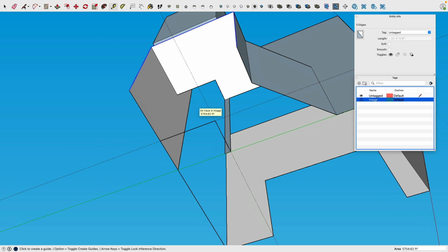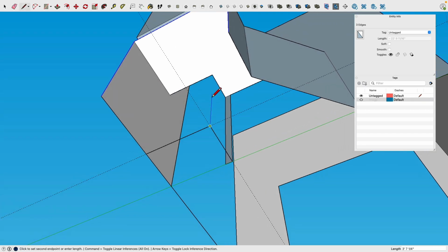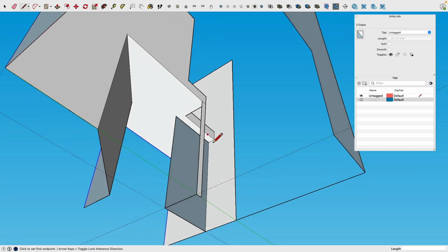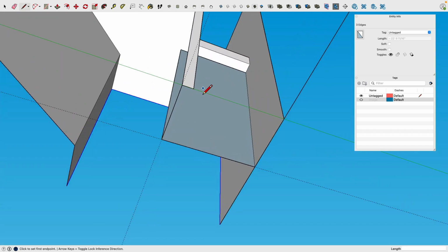This is where the door would be. So you just understand where it is. I actually model this straight up till it hits that face. Then I go along the y-axis, go down, cool. And here I will go this way, but I don't necessarily know actually how far. So I will add a guideline, 5 inches.